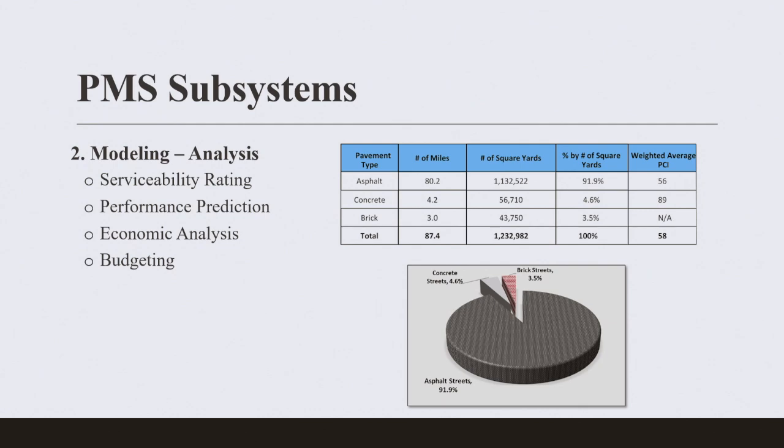So you grab this, and then basically you do the modeling and you try to come up with your evaluations as you see. You have how many miles or how many kilometers? How many of these miles score 80%? How many of these miles score 85? How many scores 50? And then you multiply the number of miles by the condition, then you add, then you divide on the number of miles. That gives you what? The overall condition rating on a network level.